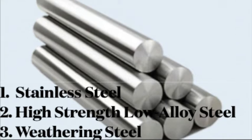Second, high-strength low alloy steel. Any of the group of low-carbon steels containing less than 2% alloy in a chemical composition specifically developed for increased strength, ductility, and resistance to corrosion. Third, weathering steel. A high-strength low alloy steel that forms an oxide when exposed to rain or moisture in the atmosphere, which adheres firmly to the base of the metal.